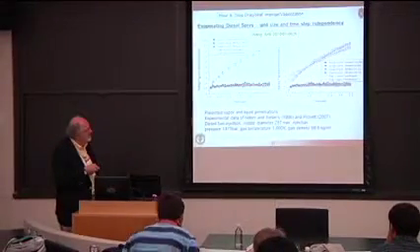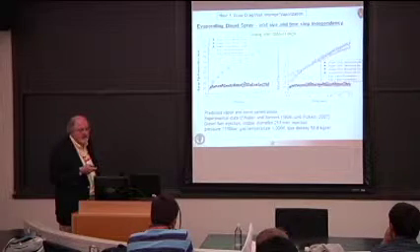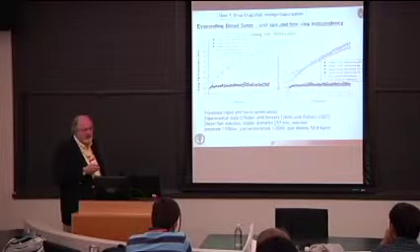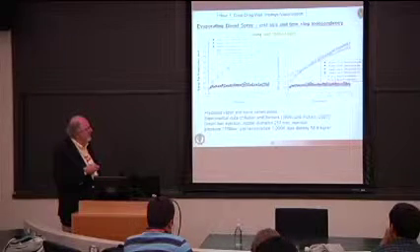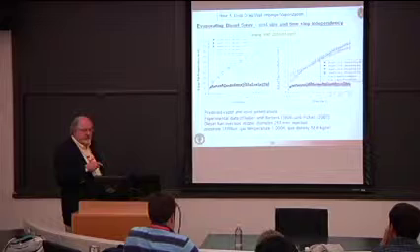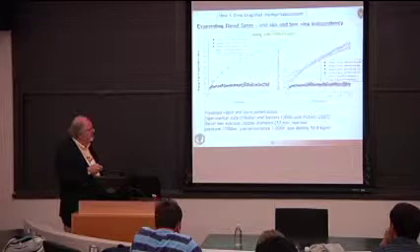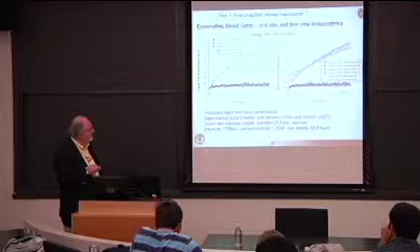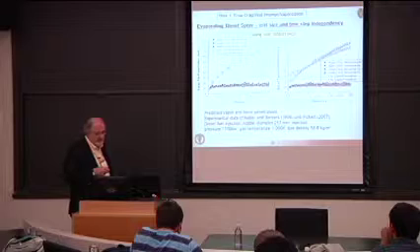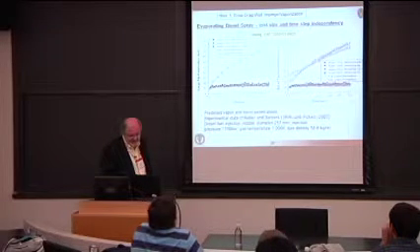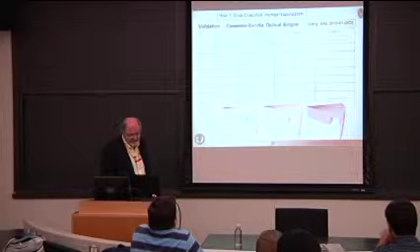The plot on the right shows the effect of time step. During a calculation, the time step is adjusted based on various stability criteria in the numerical scheme. And very few people check time step independence. In fact, you can see we do a reasonable job. There are some problems, though, when we go to very large time steps, especially at early times. But basically, we consider this to be as good as you can do at this time.